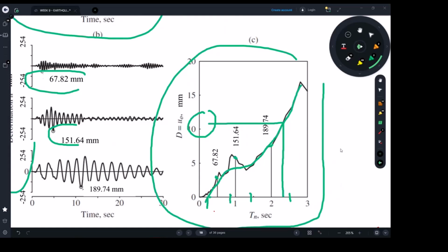Maybe if you looked at the standards you practiced for your first assignment, in the section which talks about spectral curves, they show you what you can use for Melbourne buildings. What I'm showing you with this topic is how those spectral curves are plotted from real ground excitation. Remember, the ones from the standard are done from synthetic ground excitations, which are simulated for the Melbourne region and regions within the country.